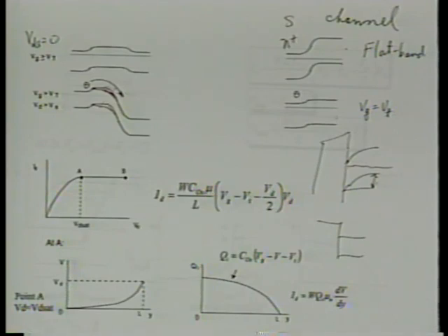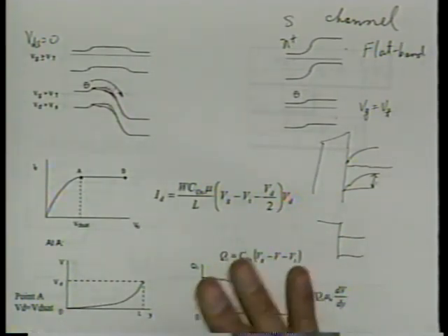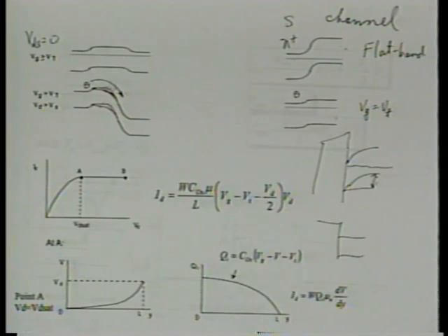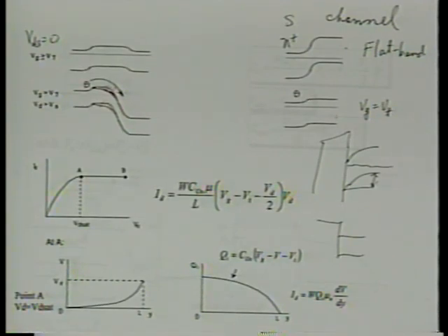And if you understand device physics a lot, then you can draw the energy band diagram. It's not like there's a certain rule you can follow to draw the energy band diagram and that immediately tells you how the transistor operates. It doesn't quite work. It almost works backwards. So the usefulness of the concept of Fermi level is somewhat limited. For that reason, we probably should not be too concerned about how to draw the energy band diagram when it's not so useful. That's why sometimes you see the Fermi level is not drawn, it's omitted.